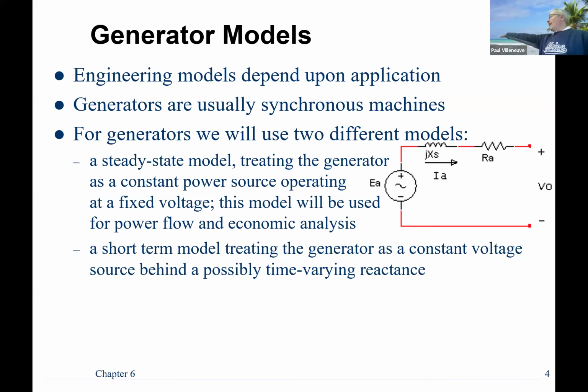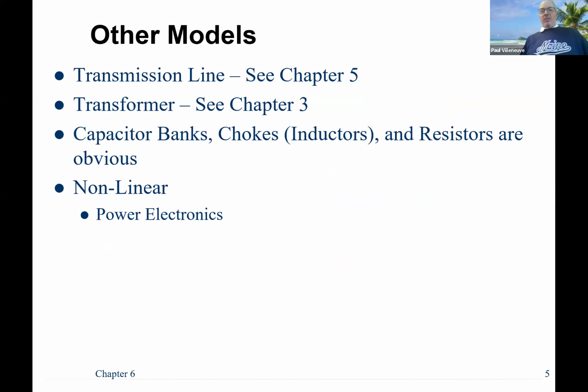Those will actually dictate a lot in terms of what the fault current actually looks like. You can go ahead and make it so that it's not a steady state. If you want a time varying model, because over the time of a fault, the fault current levels will change because you have a decaying exponential. Anytime you see an inductor, you have some energy stored there and it can decay away. And so you actually will drop your fault current as time progresses on in the fault.